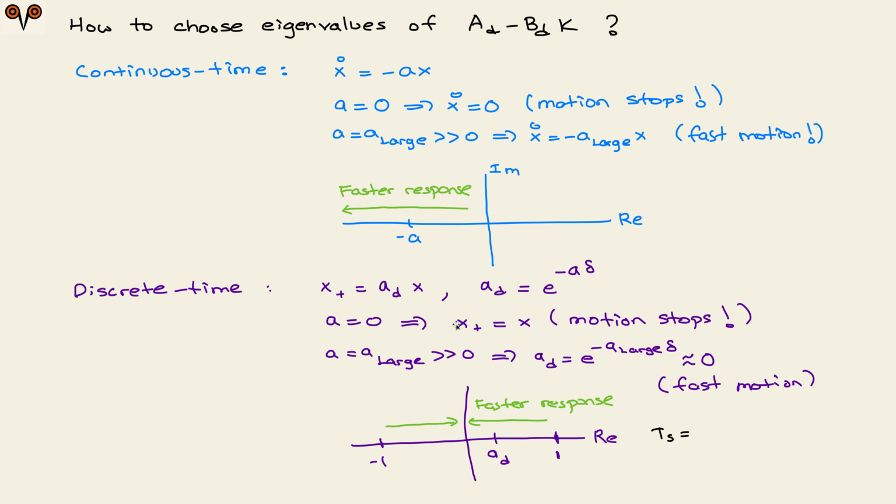So nothing changes. This is again marginal stability in the undergraduate sense, or stability in the sense of Lyapunov. Motion stops in the discrete time version as well, meaning that if you choose your eigenvalues on the unit circle in general, or at these minus 1 and 1 points, your system won't move; motion will stop if you choose AD that comes from this A matrix.